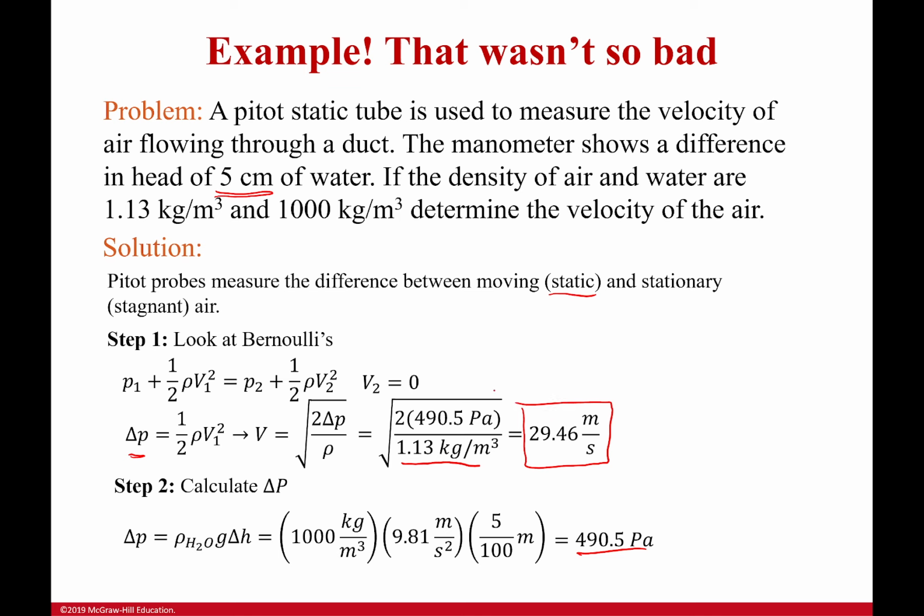So this is a very practical problem. You would be using this a lot. And you can actually build one of these yourself. Like you can build your own manometer and you can see from it how fast air is moving or the change in velocity for air as it moves through your wind tunnel.